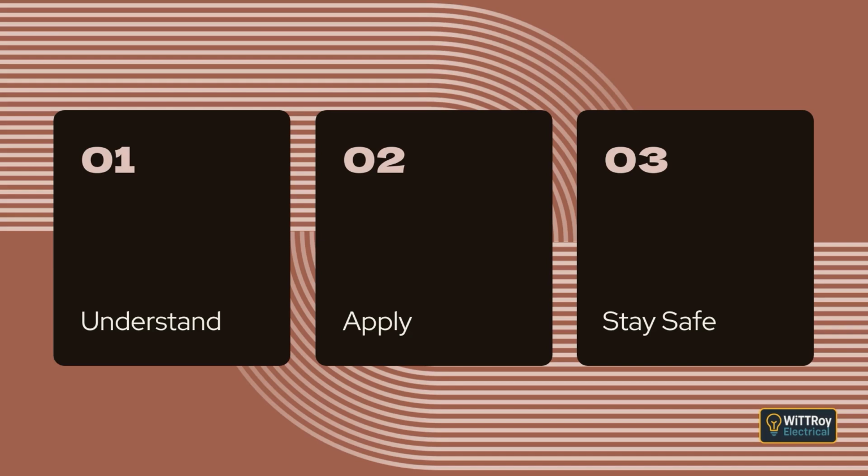There are situations where these markings are not required. If it is a single domestic home, the switchboard does not need this level of identification. If the location of the switchboard is already clearly shown on a fire indicator panel at the entrance, another sign is not needed. If the switchboard can be seen immediately when you enter the building, no extra marking is required. In New Zealand, any sign showing the location of the main switchboard must meet the New Zealand Building Code.